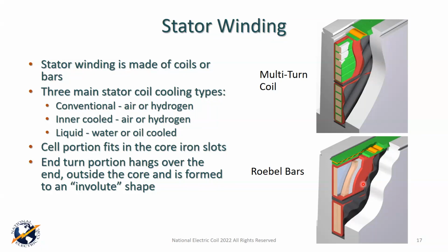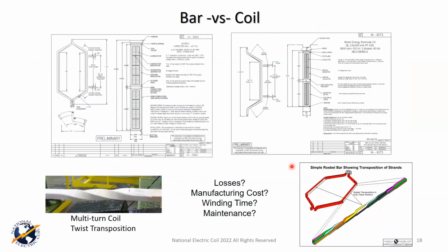Theoretically, if they're doing their job right, they help disperse the voltage so it doesn't follow a single path, which would create tracking, by the way. It disperses that surface voltage to the core and allows it to go to ground naturally. If it does that, no harm, no foul, and you do away with the potential for partial discharge and corona, and the issue of spark erosion as long as the coil is tight. We'll try to touch on that a little later as we go into some other slides. So thanks for the question, Bosco.